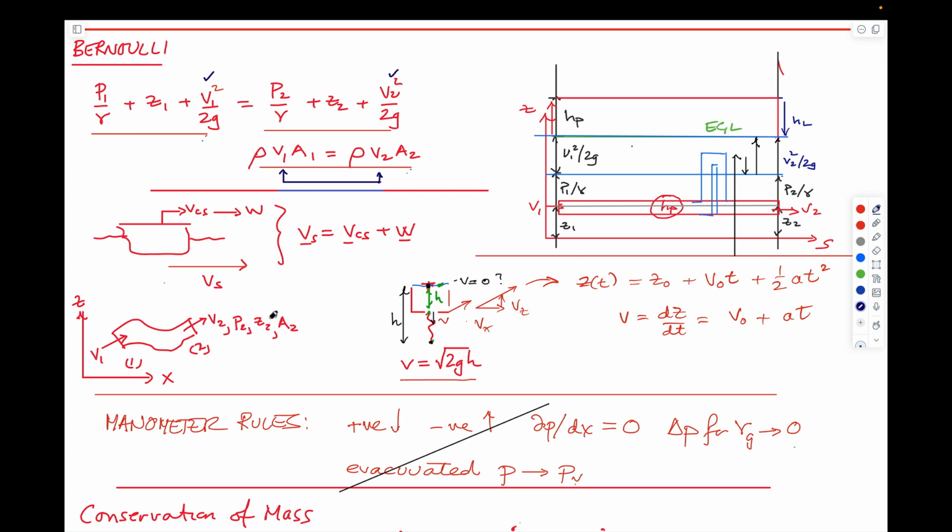We talked about static and moving coordinate systems. The fire department of New York example: the control surface is moving at some velocity, and it's squirting water out at some velocity w. To a static observer, that bead of water at the tip of this is traveling at a static velocity. If you sum these 2 vectors to equal 1 vector, then this is the relation that links them.